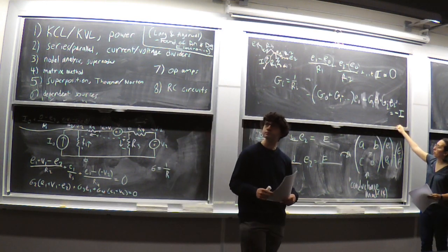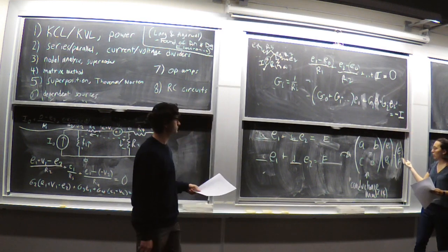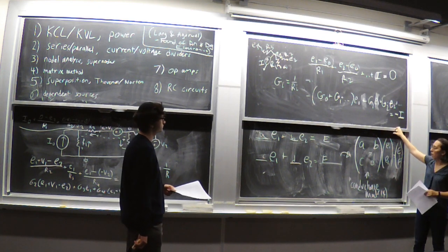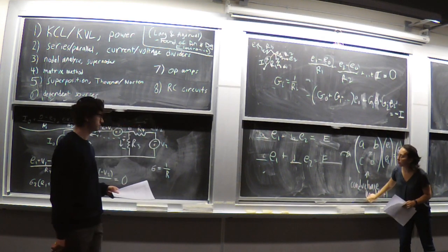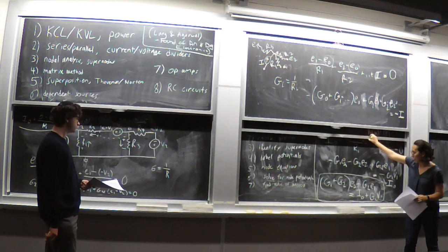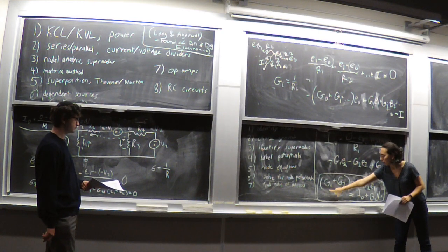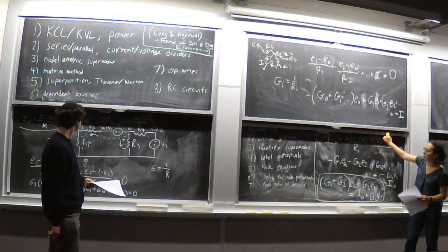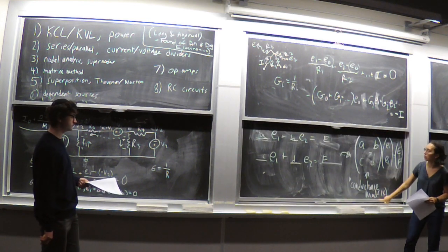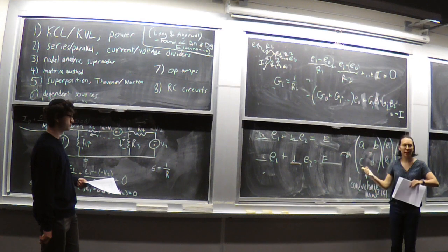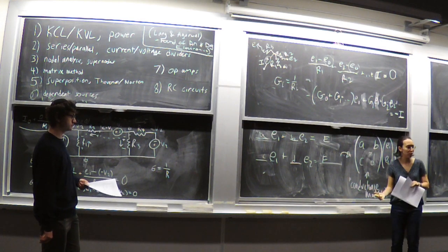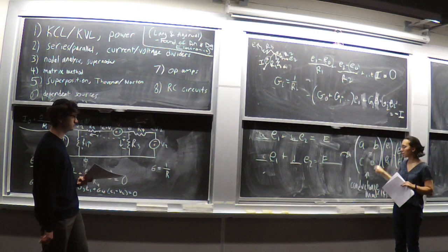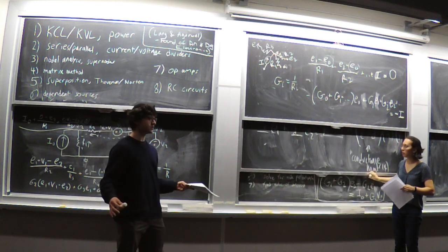So kind of in line with what we started with up here, it turns out you can actually go directly to the conductance matrix just by inspecting the circuit. So what we were seeing in our equation here, when we had the sum of G1 and G2 times E2 and minus G2 here, we actually will end up with that form in our conductance matrix. So you can solve that out. Come ask me at the end if you want to see the formal derivation of what the most general conductance matrix is. We won't go through that now, but you can go through a process like this.